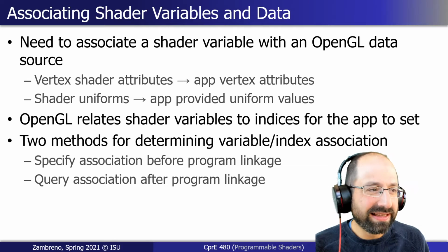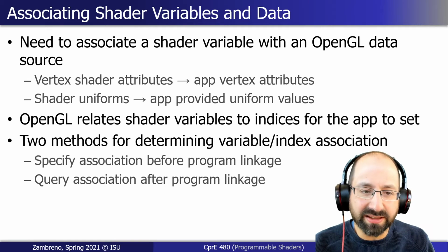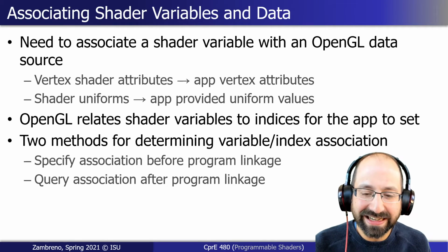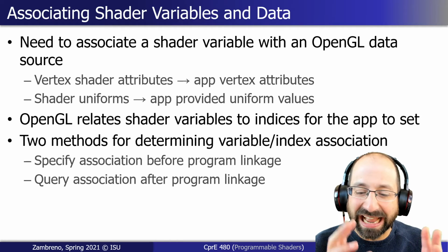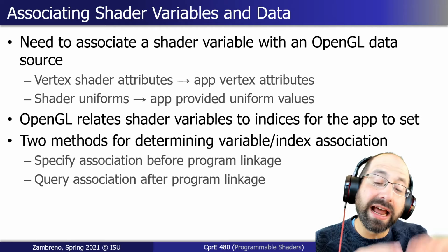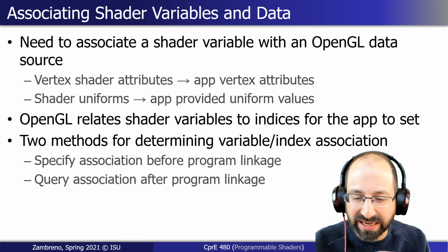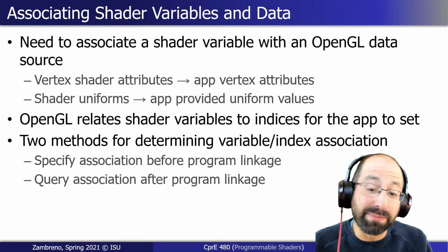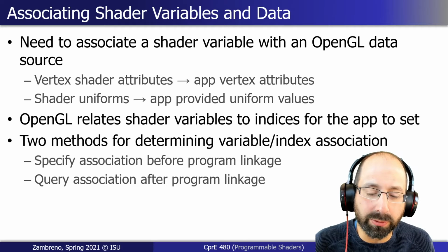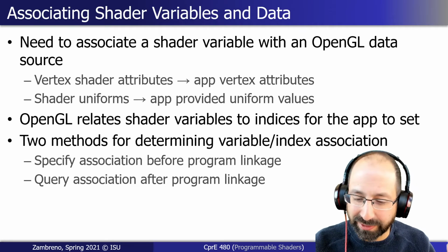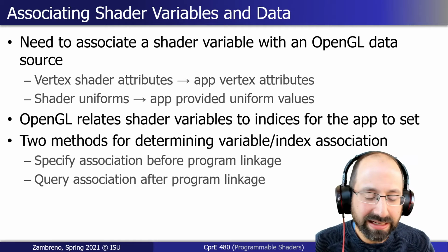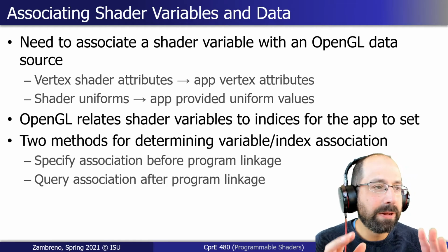We've been saying, well, it'd be nice if you could flush the cache in your render output, so your triangles don't look so jagged at the very end of their render. It'd be nice if you did it. Some teams kind of did it, other teams kind of sort of didn't. It's imperative now, right? Your shaders do not work without flushing those data caches, and they also don't work all that well if you don't flush the instruction cache as well. But you could always find workarounds for that.